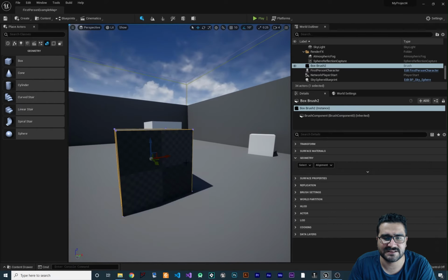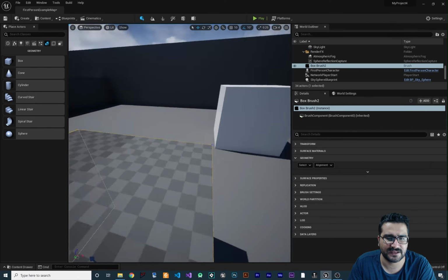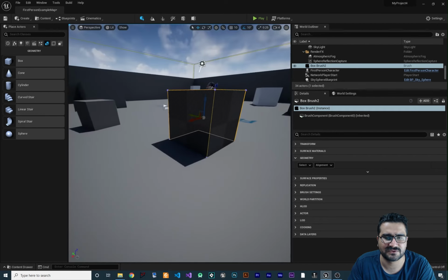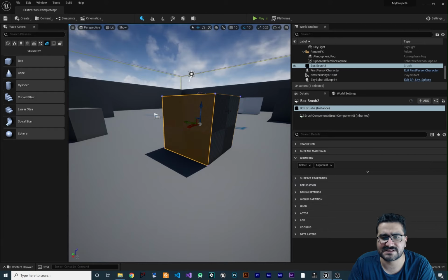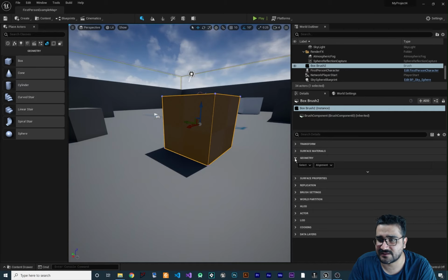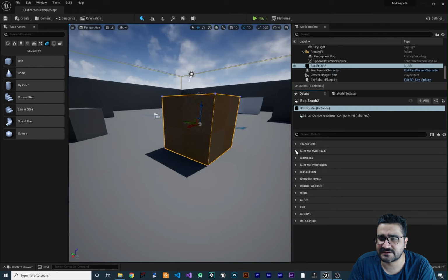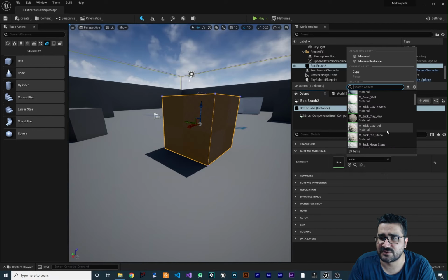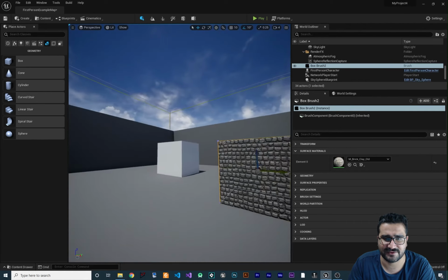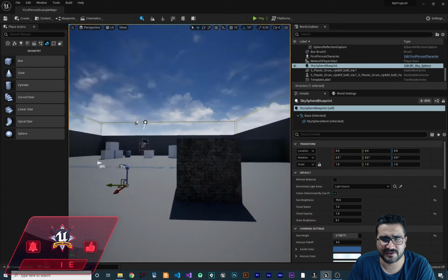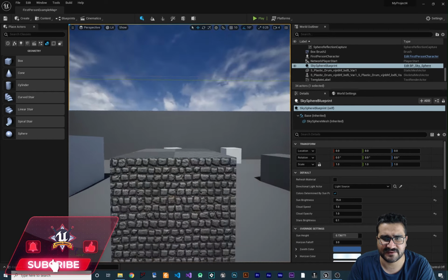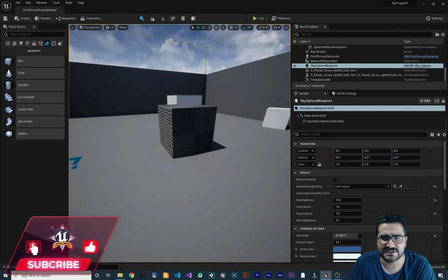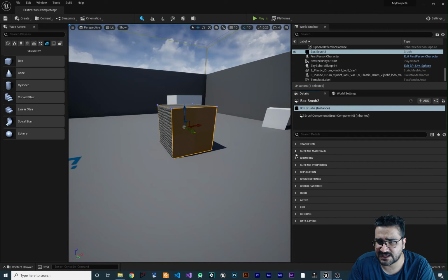Again, we can select these, hold control, select this side, again hold control, select this side, hold control, select all of the sides with holding control, and after that go to just collapse this geometry and expand this surface material and apply a material to it. One way you can do it like this, and you can see that it's applied to whatever surface that we selected. Another way to do it, just select one side and let's just collapse this.